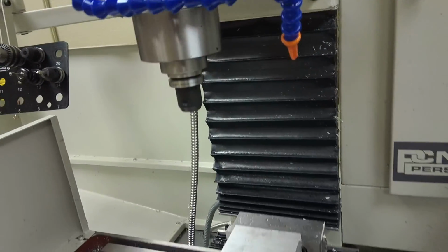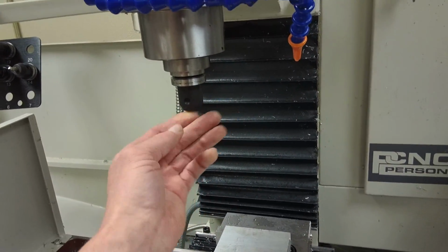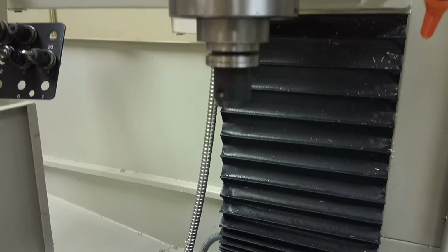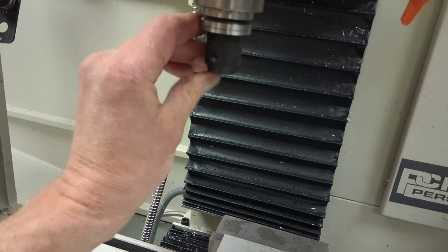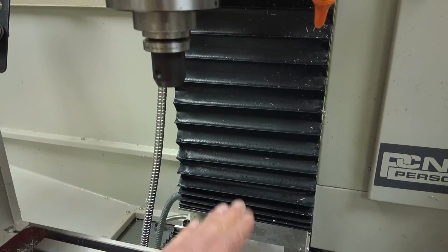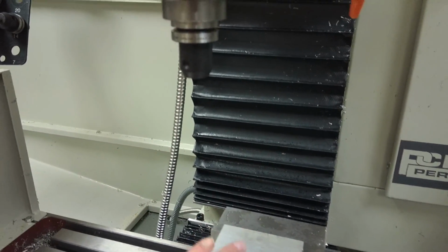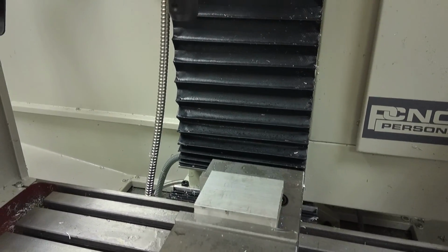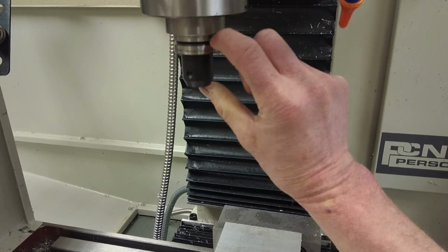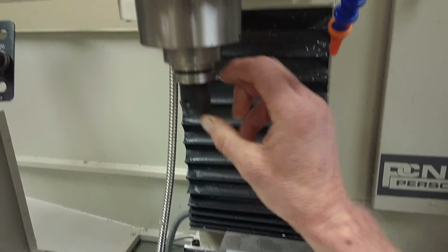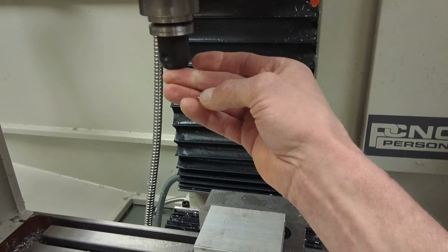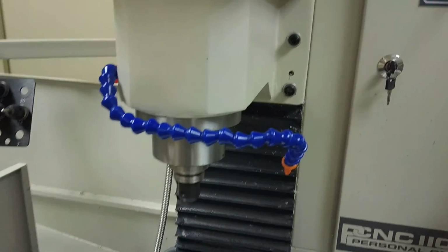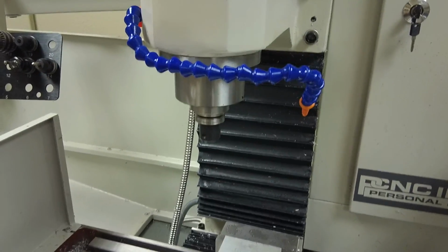And so what we're going to do is we're going to use what we call tool number 0. This is just an empty tool holder. And this is what we're actually going to use to touch off of our part and find exactly where the surface of that part is. So first we need to measure this. We'll set that to our 0, and then we'll come in and measure the relative length from that surface for all of our other tools.